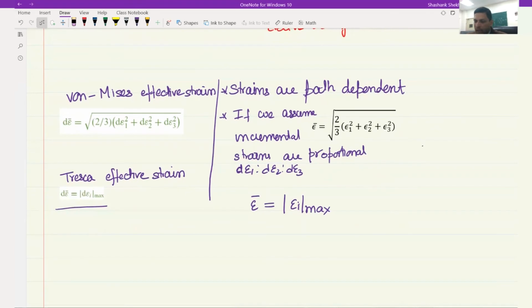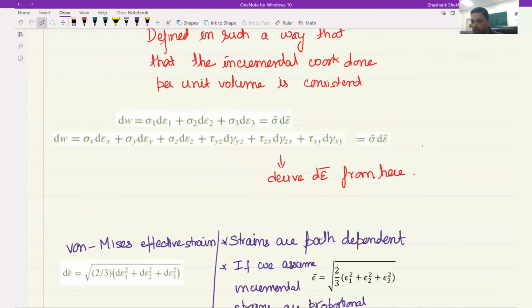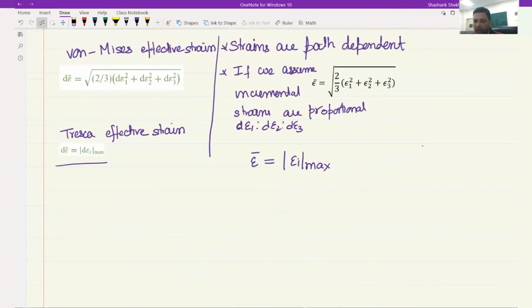Okay, so now let's look at a uniaxial stress condition. What will happen in the case of uniaxial stress condition? We have already seen the stress part. Now let's look at the strain part. What will happen to the uniaxial strain if we are looking at a uniaxial stress strain curve? Uniaxial tensile condition. So here we remember that the primary strain is happening along the direction in which you are pulling the dog bone or your sample, and two lateral strains are taking place in perpendicular directions.